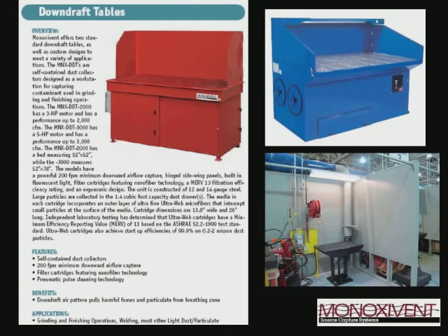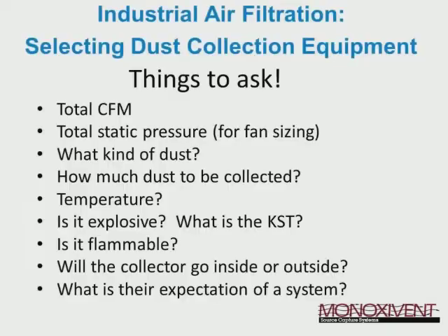With that being said, there's three units shown up here. The red and the blue are self-contained. So if you're designing a system and maybe you want a self-contained system, those are great ways to do it. They have the fan and they have the cartridge built right into the system. And then the one at the bottom right is ducted. So if you look behind it, you can see the duct work, and that's being captured and then in this particular case sent right over to a dust collection system.